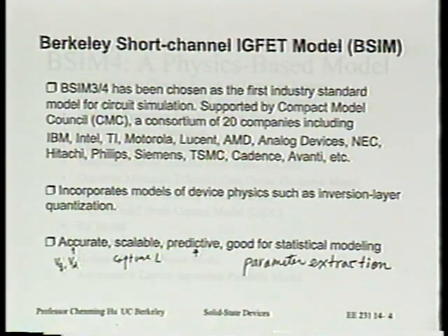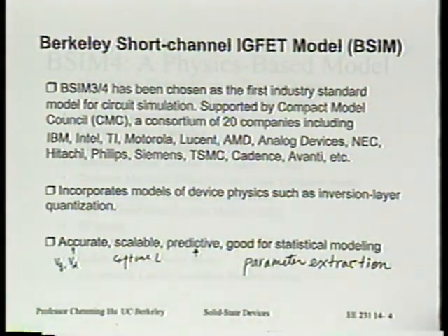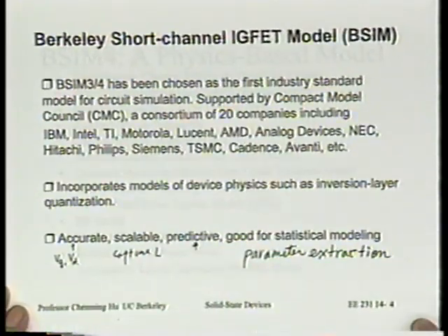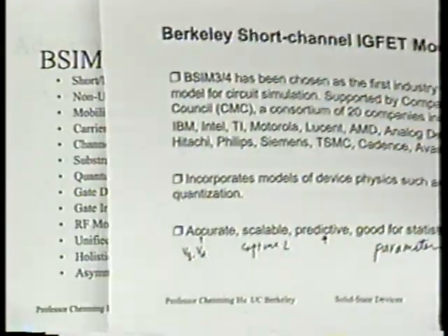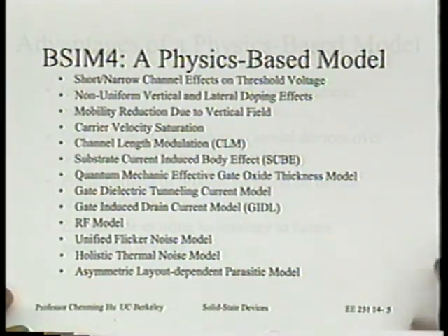So actually, even the parameter extraction has become easier. It used to be that a company thought they were going to need months to characterize a model, meaning take months to determine the model parameters for a SPICE model. But today, companies claim they can do this in minutes. So that is the kind of difference that it could make.